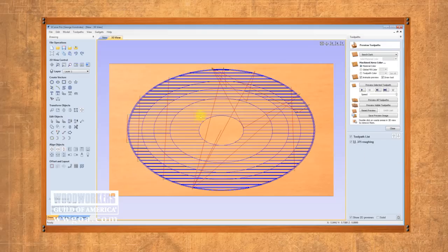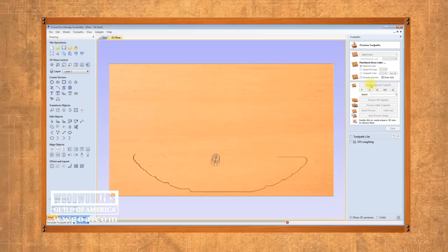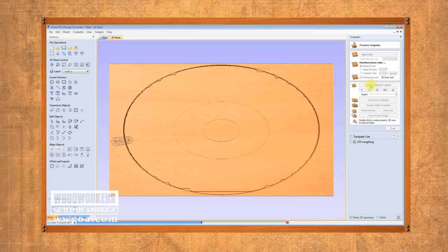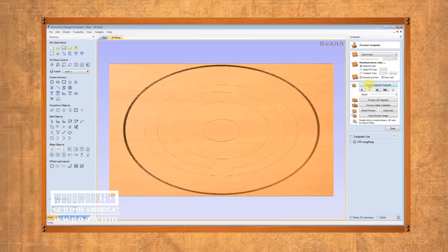This is the tool path we're looking at. What's really cool to check your work is let's use this part of the menu, preview tool path. That's our router bit. Excavating, excavating, excavating. This is going to give you a visual idea of, did we do this right or not? Now this is looking at it from the top down.